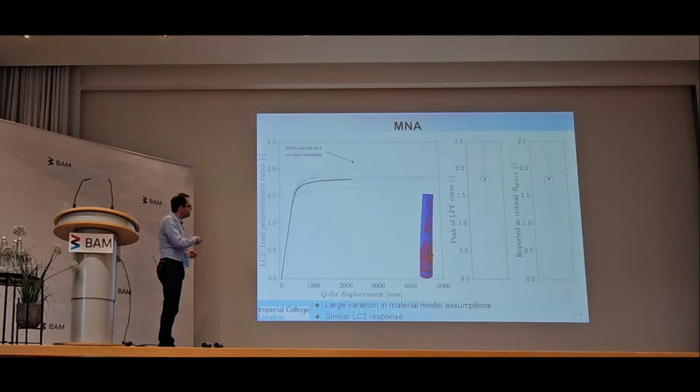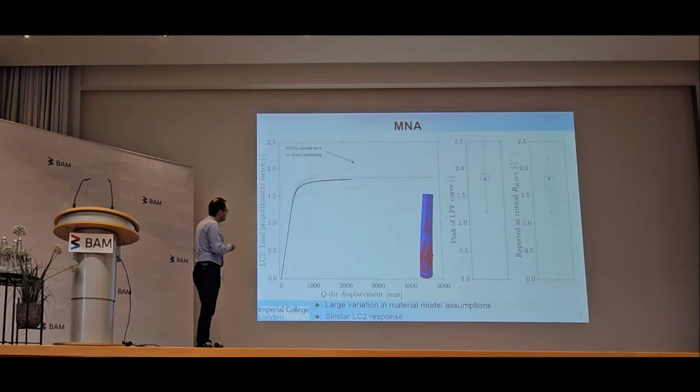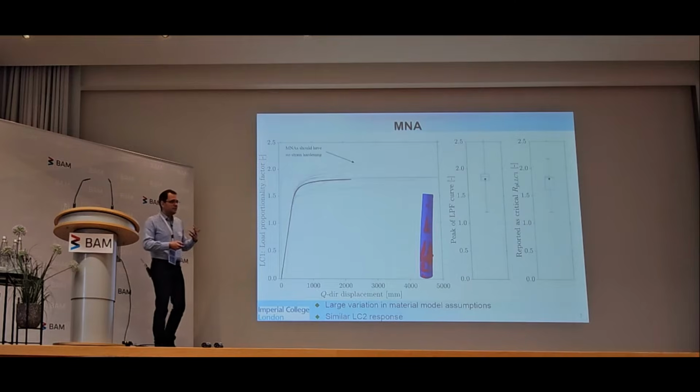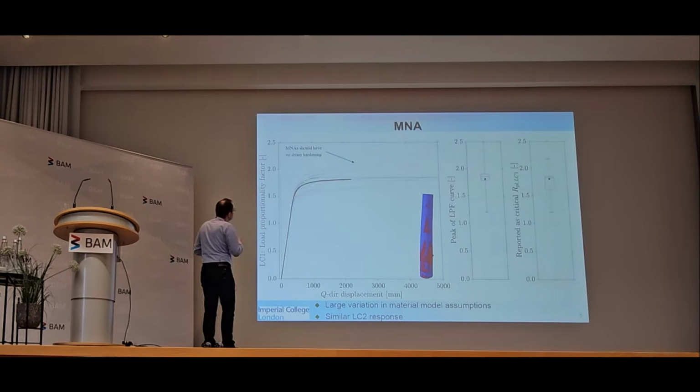And there is quite a lot going on here. Some of these are simply incorrect. Some of them have very low plateaus. I'm not sure why that is. Quite a lot of them do follow the reference result, and they are more or less okay. And I think the variability around there is probably due to meshing. If you have a coarser mesh, you will once again get a slightly stiff response. But some of these results have just too high a gradient.